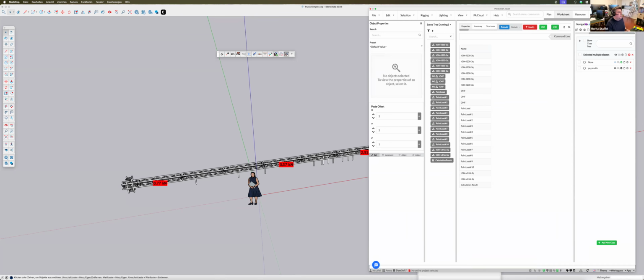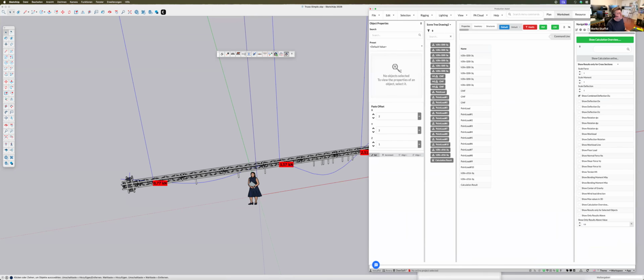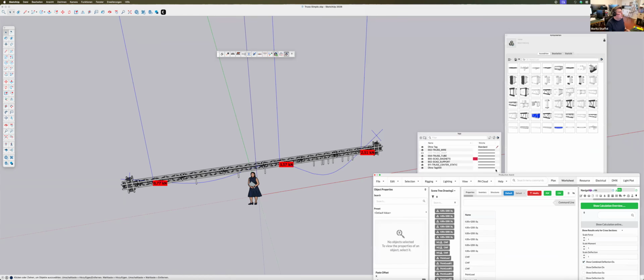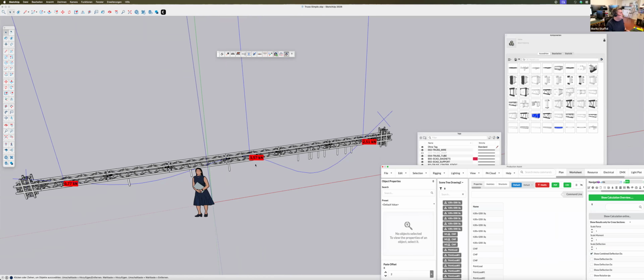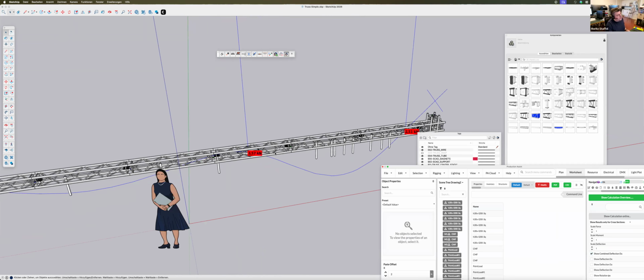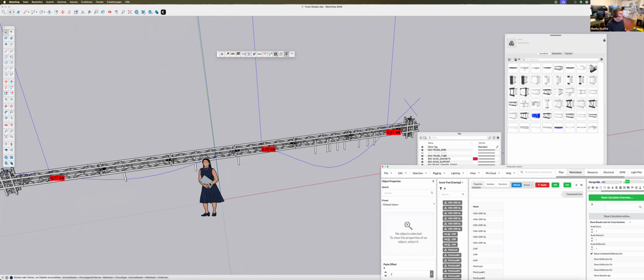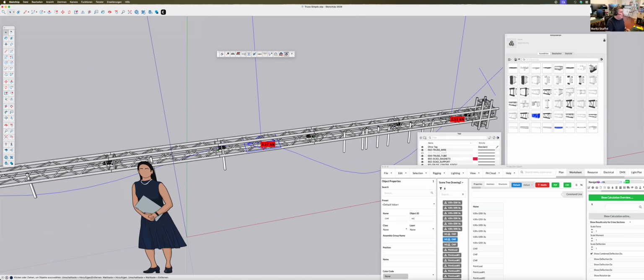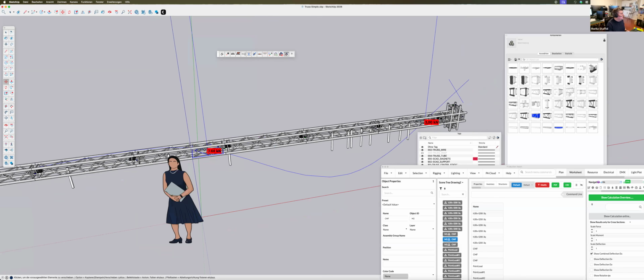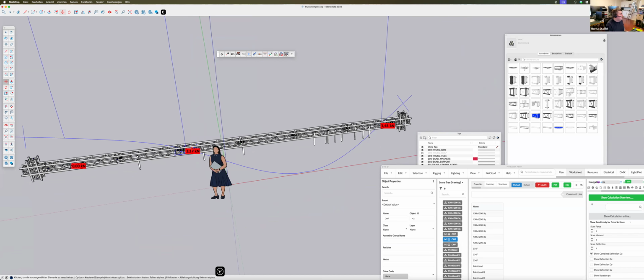When you now, for example, go to the influence lines and show the deflection figure, you will see directly this deflection figure is also shown in SketchUp. And in addition to this, it also shows you the forces that there are in the motor. So now when you click on the motor which has been inserted here, activate the move tool and move this thing, every time you're doing this, you will see it's actually changing the forces on it and updating the calculation engine. It's quite convenient to work with this.